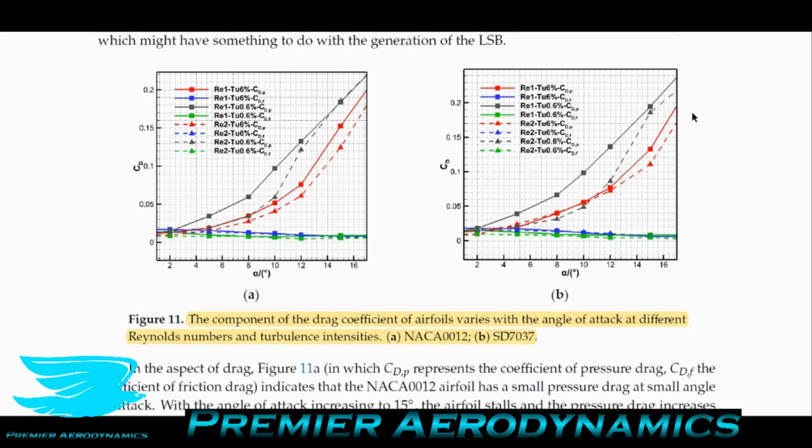And then you get wave drag, which is when you go near the speed of sound, or if you're swimming in a pool, again, you get the fluid above, it creates waves. With the speed of sound, you get this compression of air in front of you, and they're generally characterized as wave drag. Again, they're different concepts, but they're different components of drag, and the total drag coefficient is made up of all of these components together.